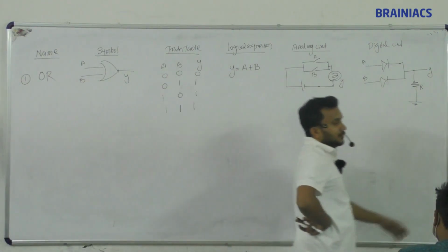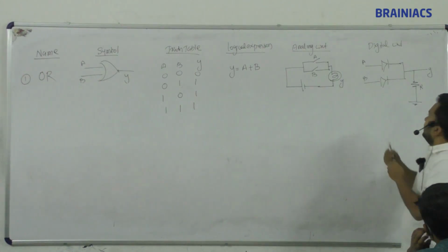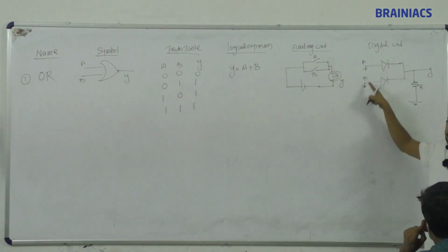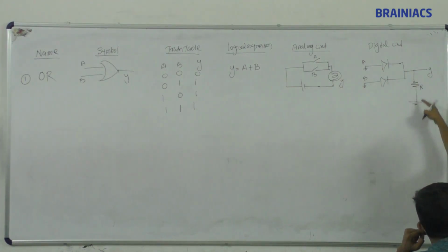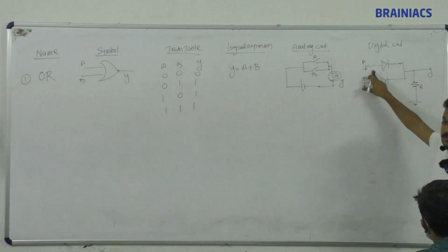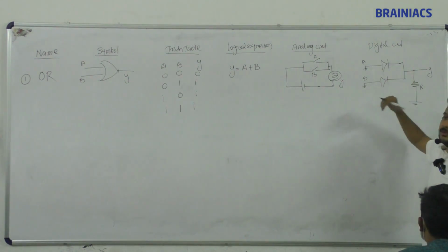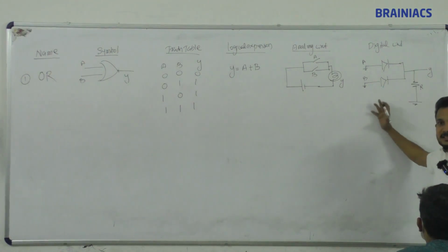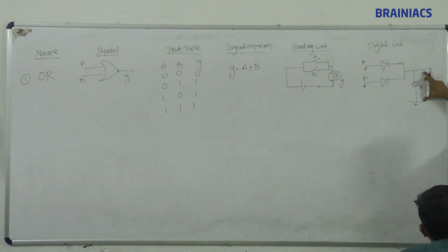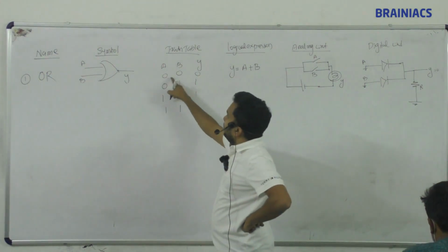This is most important. This is the real question where NEET falls. You are giving 0 0. Once you see 0, you have to assume it is grounded. That's all. Don't draw it in the book. Now this is for the 0 0 condition. Both sides are 0. Diode forward bias or reverse bias, we cannot say. The diode will not work. To work, the diode must be in forward bias with higher voltage on the anode side. This voltage is not higher, right? Both sides are 0, so the diode will not work, similar to a reverse bias condition. Y is the output. Output means the current flowing through the resistance: I into R is equal to Y. Now both are grounded, so Y is equal to 0.